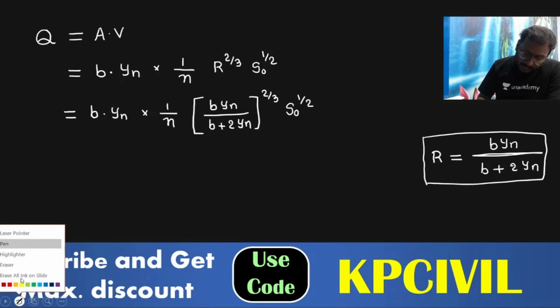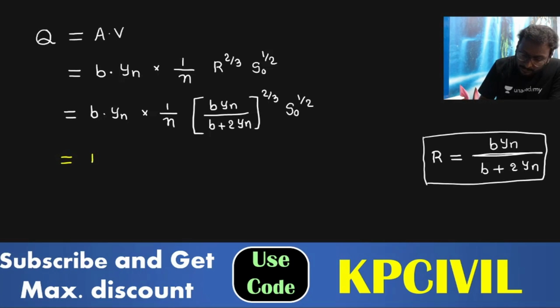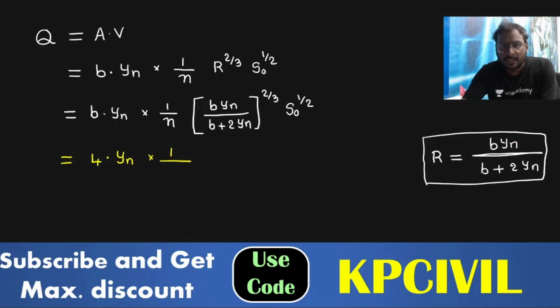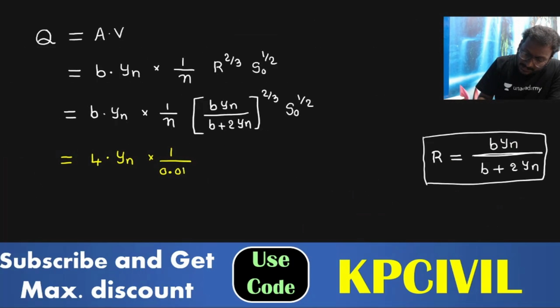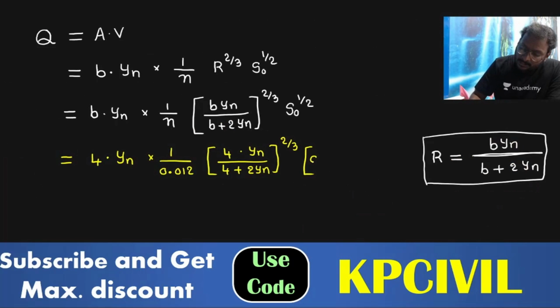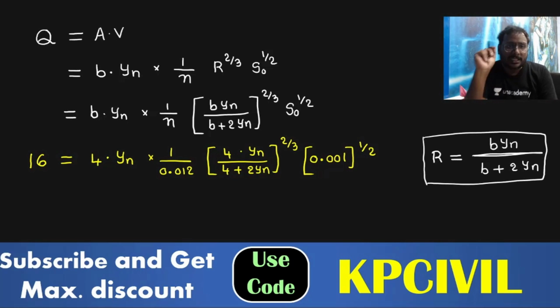Now I am going to substitute the values. B is 4 meters, Yn required, into 1 by Manning's coefficient, which is 0.012, so 1 by 0.012. Then B is 4, into Yn, 4 divided by 4 plus 2Yn, whole power 2 by 3. S is given 0.001, 0.001 whole power 1 by 2. Discharge is also provided, the value 16.